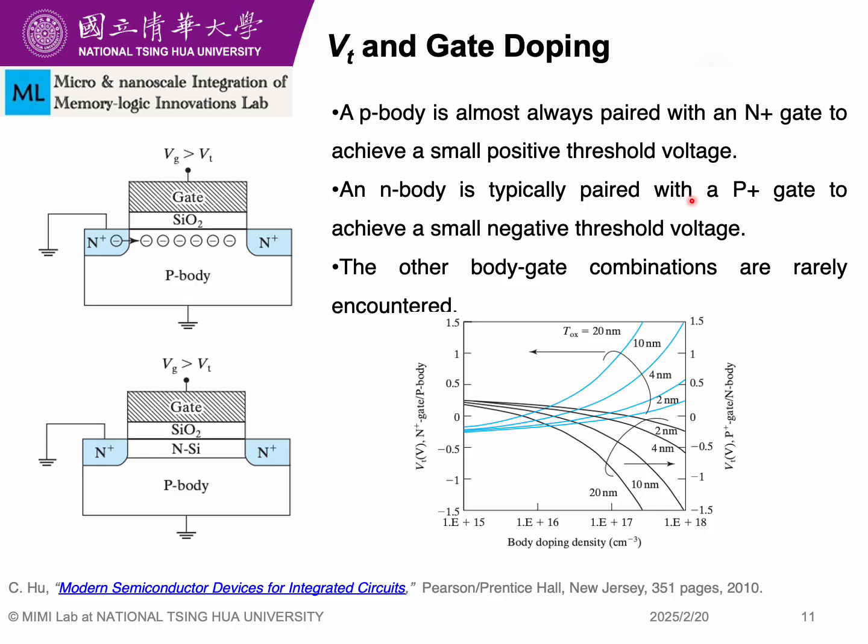And what do we want? We want a small Vt, like below 1 volt, like 0.4, 0.3, but it should be larger than 0. So at 0 volt, there should not be any current. And this is called the enhancement type MOSFET, that does not conduct at 0 volt.